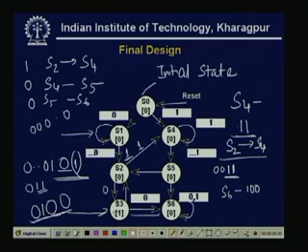That is why, when the present state is S3, S3 recognizes 0 1 0. Now if a 0 comes, then the 3 consecutive input bits will be 1 0 0, which is recognized by the state S6. That is why the S3 to S6 transition has occurred.